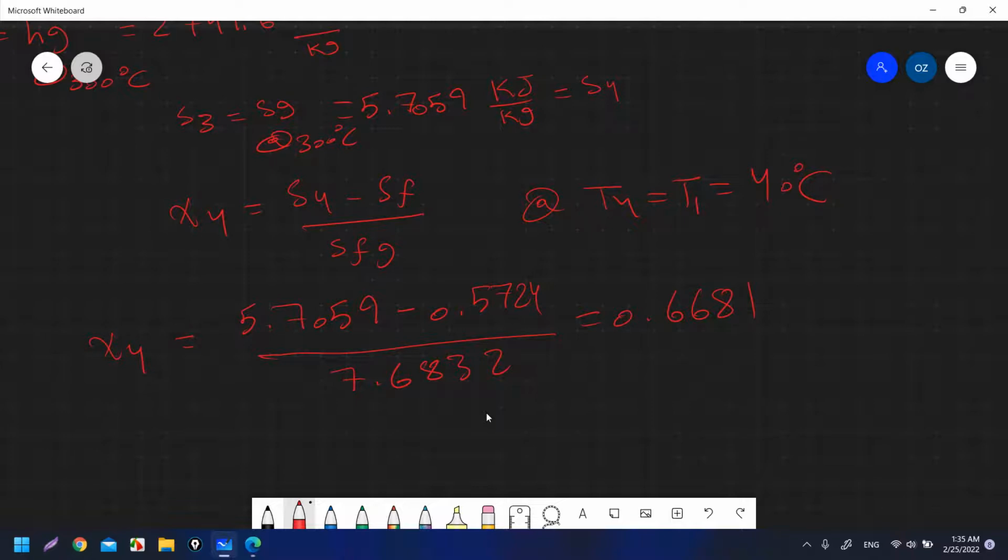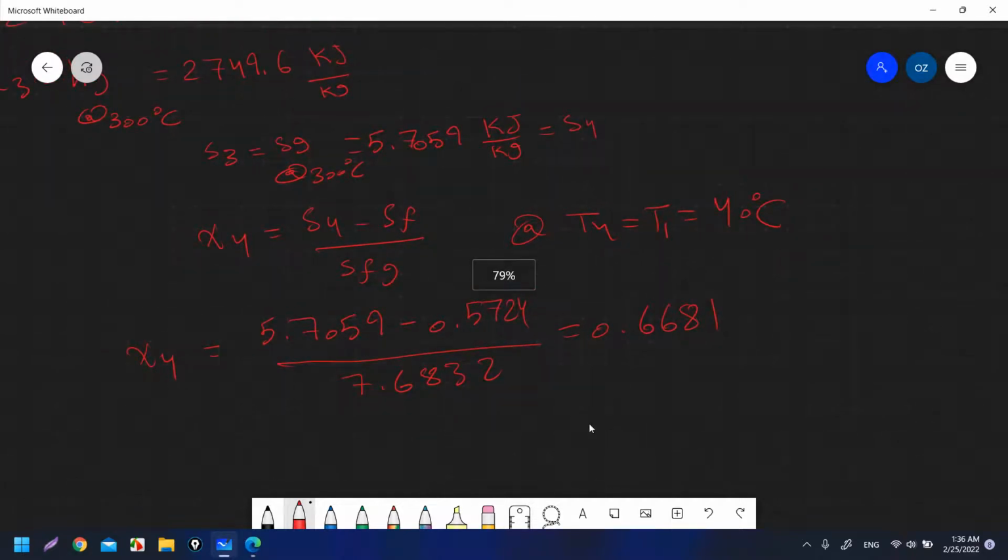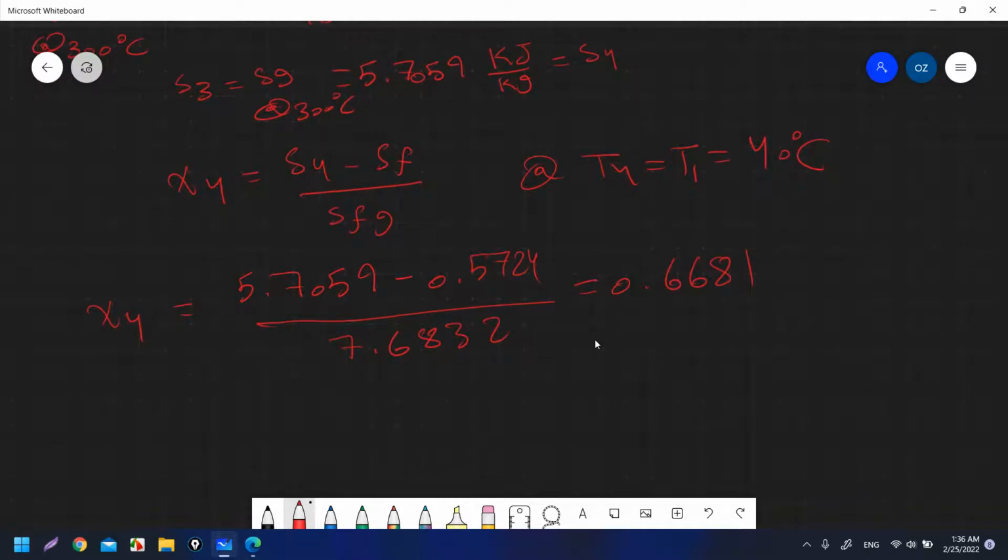for the turbine, for the outlet of the turbine, to be above 0.9, because the droplets of liquid, if you have water, will affect the blades of the turbine. Okay, so we want it to be dry, and we don't want to have water. So X4, that's a bad number, but that's what we have in the question. Okay, who cares?